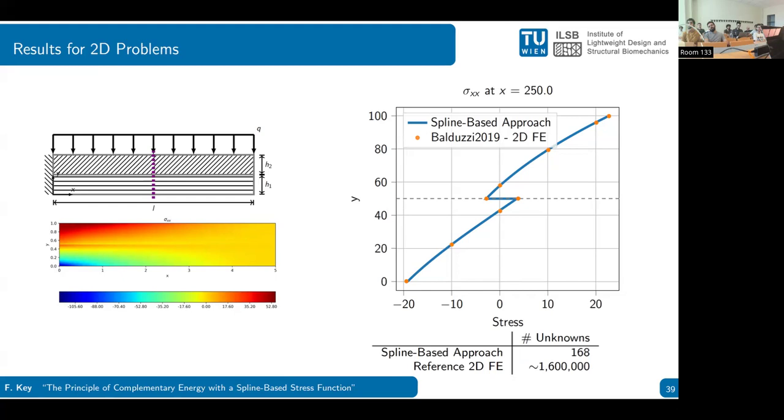As I said, that is why I also presented it that way today. I think even if you forget about the quantum part, it's still very relevant and interesting as a numerical scheme to get high accuracy stress predictions with a very small number of unknowns. So you already have a huge reduction there with the same accuracy, plus you get the regularity for the stress function, which is something you always want.